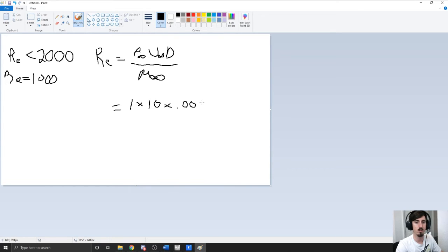Now, this is standard units, so the normal equation is in meters, so that way our velocity is in meters a second. We set our model up to be millimeters, but we'll have to convert for our formula. And then this is all going to be over our viscosity of the fluid. And actually, sorry, this is 10 millimeters, not 1 millimeter.